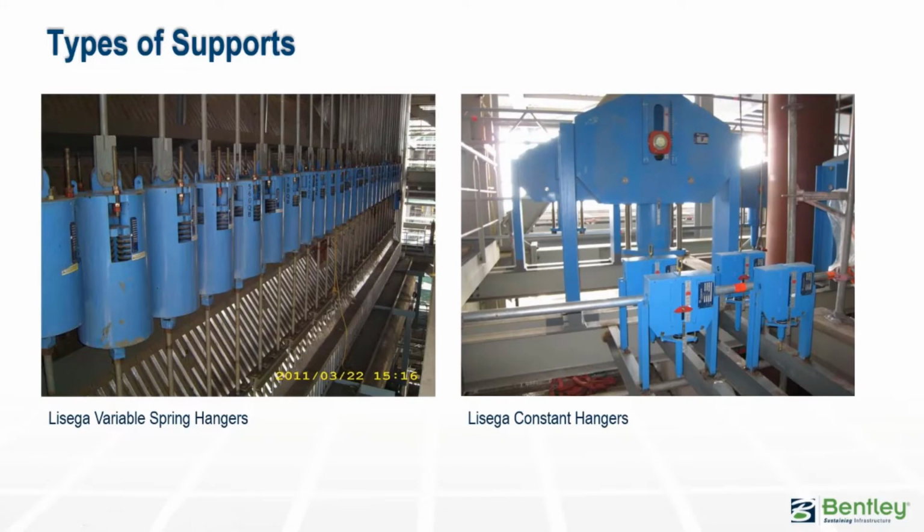There are also constant spring supports, which have an arrangement of levers and cams that provide a fixed amount of constant support force. These are more expensive supports, but they're ideal for where pipe movements are large and the sensitivity of equipment is important. So as an example, in a main steam line. And they also have different types of these for different applications.